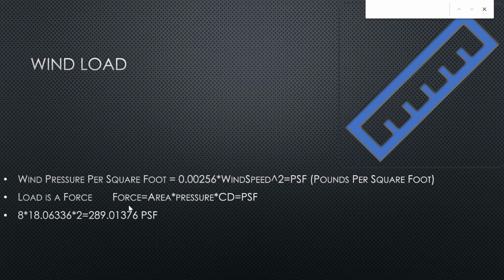Using this formula, we find the pounds per square foot of our sign, which is pretty massive. I used the highest recorded wind in El Paso to solve for this, because you asked for it under the most drastic, dire circumstances, which happens to be 86 miles per hour.